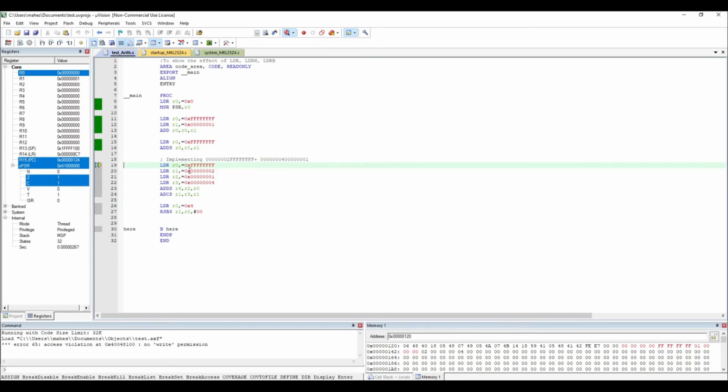Now let's move on to the other one, which is 64-bit addition. It's quite straightforward. This is the addition that you want to perform. I'm going to store it in 4 registers, and then finally I will add the least significant word, 32 bits, and I will consider the carry also, so I use ADCS, that is add with carry, and update the flags as well. If I had used ADD here instead, we would have been in big trouble, because I should consider the carry also when I add the most significant 32 bits, right? So that's why it's very important to play with.